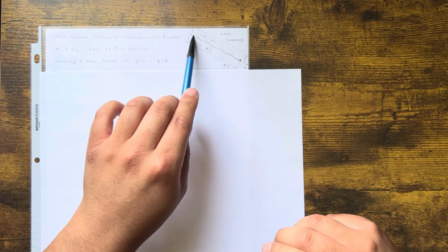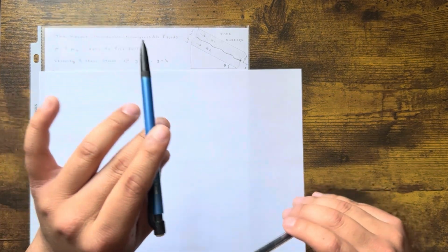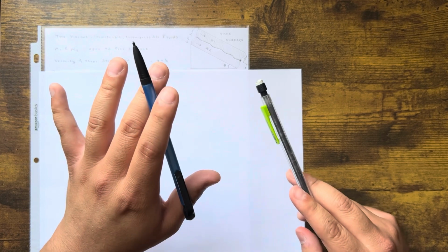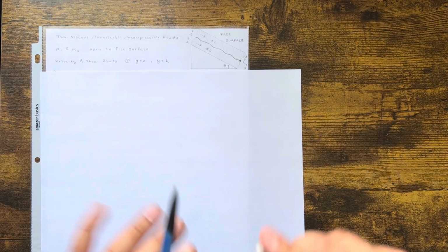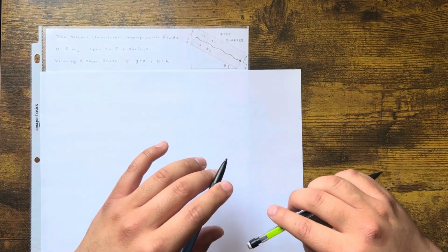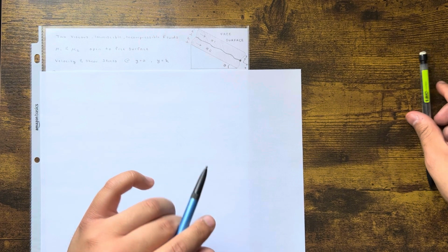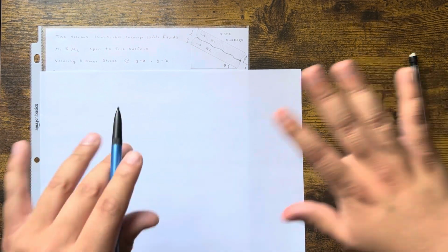In this case, I do 0, h, negative h. It doesn't really matter, because the only thing that changes is your general solution. But at the end of the day, your velocity profile should stay the same as long as you got the correct answer, and I'll tell you where it changes direction. The first few steps deriving that reduced Navier-Stokes equation should be the same regardless of where you choose the datum. That only comes at the boundary conditions.